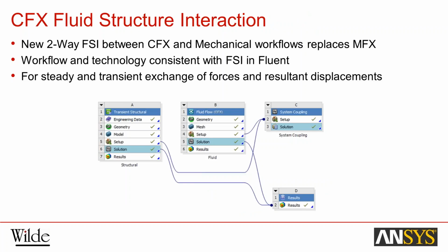Fluid structure interaction is worth mentioning. Previously, CFX used what was called the MFX connection method, which is a direct connection between CFX and Mechanical. It now uses the same system effectively as FLUENT, where everything goes through a System Coupling box. This should make the workflow considerably easier.